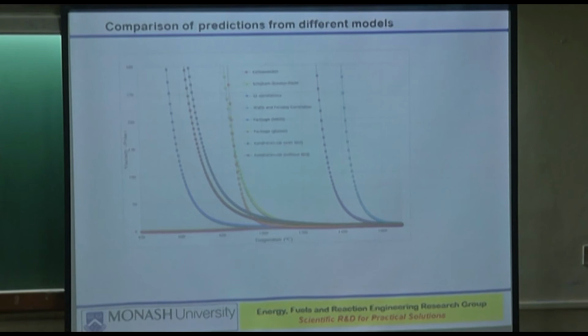So we eventually decided that inside the furnace, close to the molybdenum crucibles, we will put graphite blocks that will last for about 20 hours. The graphite will soak out the oxygen before it comes in contact with the molybdenum. That became a lot of exercise, finding out and then perfecting it.